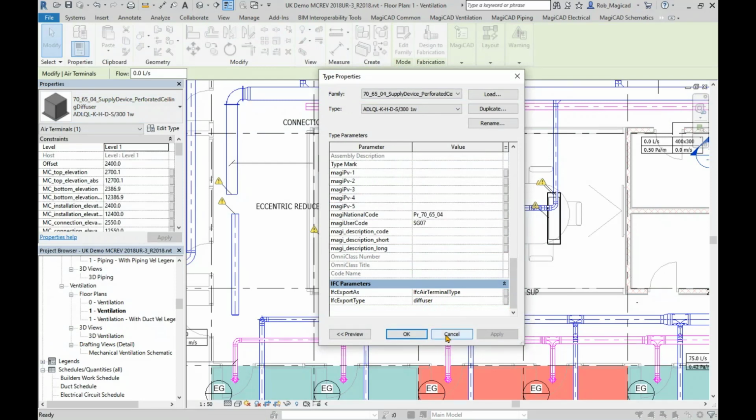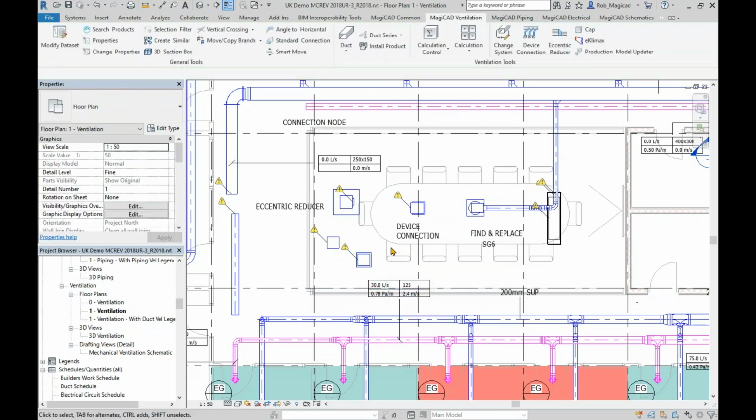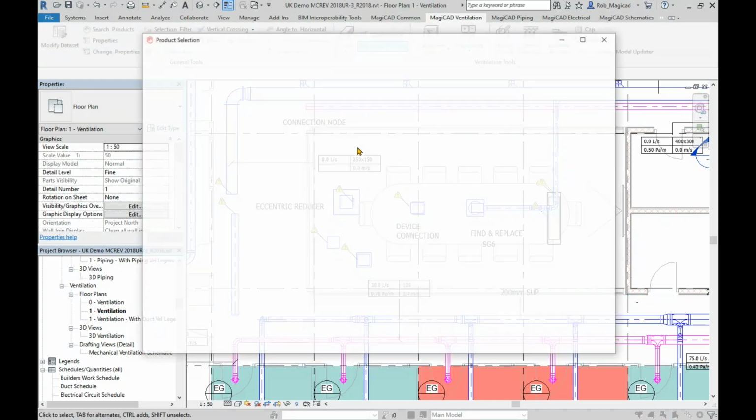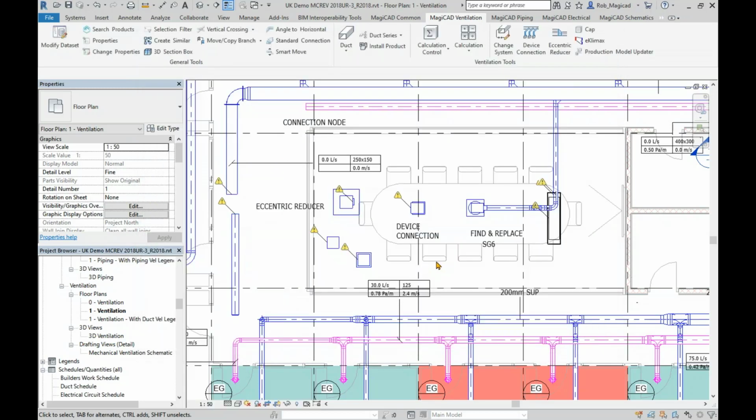So what I've done there, I've gone into my properties, created this condition with these properties of IFC, pushed it into the project, and it's updated any family of that kind that already existed. And of course, if I installed it again now, then clearly it would also continue adding all those IFC types into the project as normal.